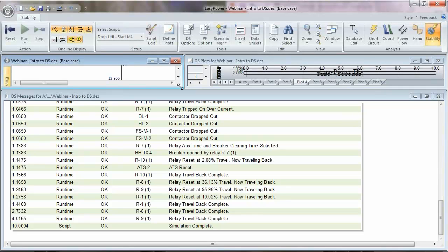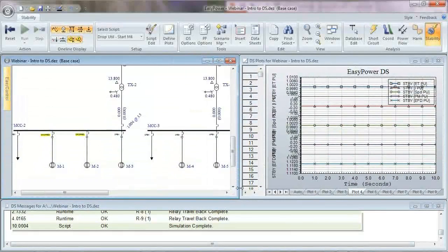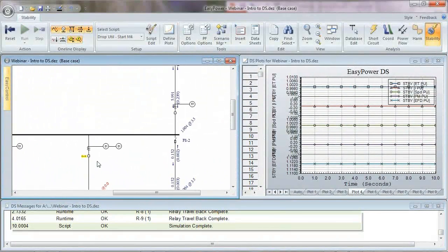Now, note here, you may not see this on a time current curve. Just understand, we are simulating the decay of currents in motors and generators in full detail. So you're going to see a lot more response. I mean, you might have actually seen a trip in a TCC, whereas here we're saying, well, we just squeaked under, or maybe we were a little better off than we thought. Okay? So, boy, relay 9, I believe, if we go up here, that's this one. So we may want to check our selectivity and maybe go over our protection scheme in a little bit more detail to make sure that, yes, indeed, we're tripping off devices in proper order.